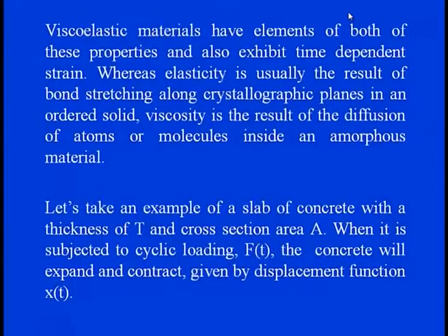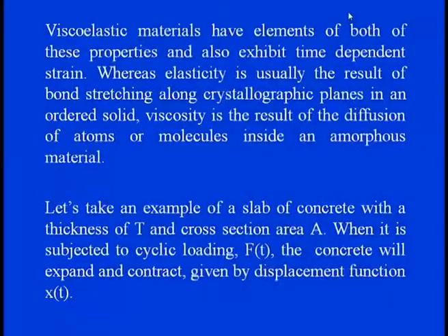Whereas the elasticity is usually the result of the bond stretching along the crystallographic planes in an ordered solid formation, and the viscosity is the result of diffusion of the atoms or the molecules in an amorphous material. So you see here, this is the interfacial structure of these viscoelastic materials: we have the elasticity, which is mainly due to the bond stretching along the crystallographic plane, and we have the viscosity, which is mainly due to the diffusion of the atoms or the molecules in an amorphous material.